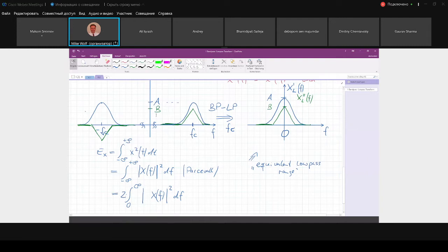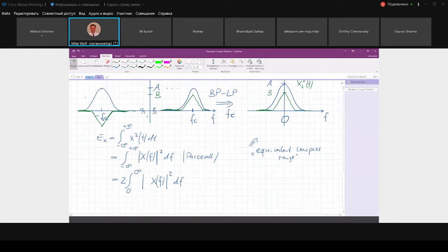So if we go back in the time domain, these signals oscillate with this frequency fc, and this doesn't. We delete the left-hand side because if we shift the spectrum, yeah, we can shift the right-hand side to 0, but then this spectrum would be at minus 2 fc if we still have it, and this would help nothing because then the time domain signal is still complex, yeah, and still oscillates. So we want to delete this, but you will see it later in the examples.